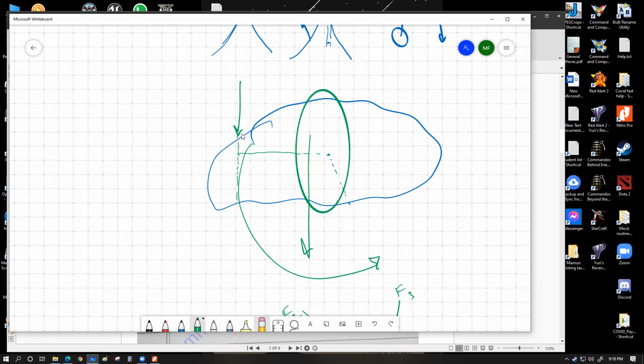Once this application of force stops, try to understand, this object would once again return to zero equilibrium force and zero equilibrium moment. But the object would keep on moving in a straight line while spinning on its own axis about its center of gravity. So if an object is seen to rotate, it doesn't necessarily mean it is under the effect of a resultant moment. A visibly rotating object could have been under the effect of a moment which started the rotation, but it doesn't necessarily have to be under a moment right now, because if you have an object that is experiencing a moment right now, it should speed up the rotation.